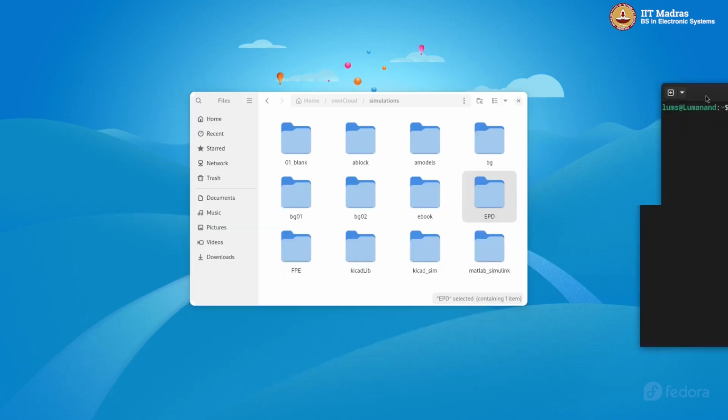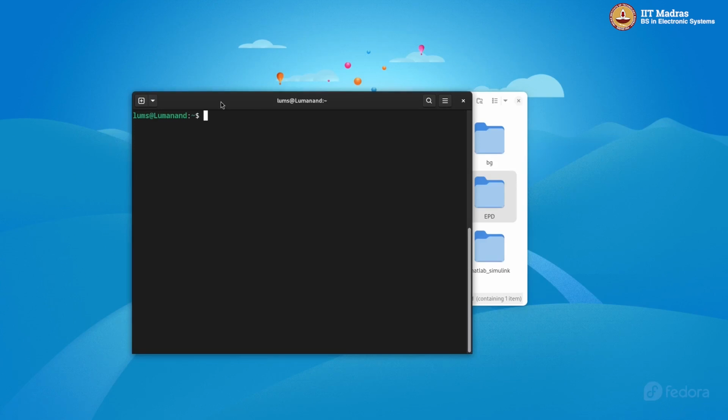So now let me pull in a command window and install both KiCad and ngSpice. On Linux, it is pretty simple. You can use the package manager, and the package manager will search for ngSpice and KiCad in the repositories and install them along with the dependencies. You must have some exe file for Windows which will set it up. I think you will find the correct installation file for Windows and Mac OS also.